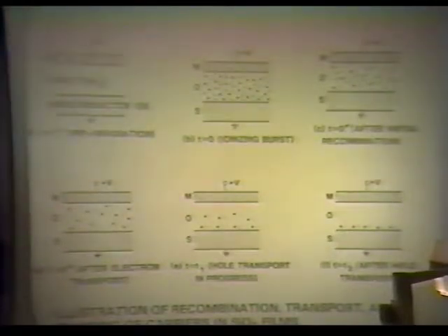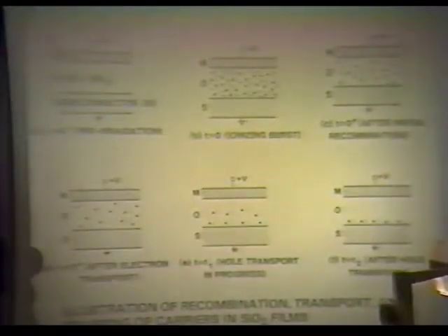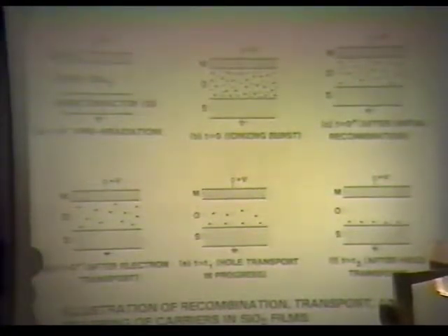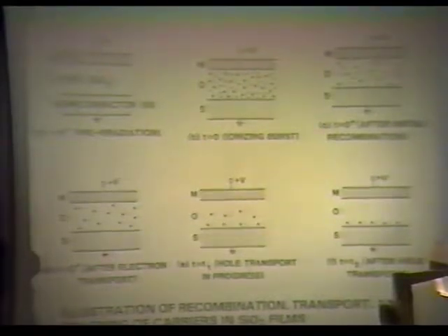Now neutrons, they haven't done much. They've created defects in the silicon here, but you've got so many donors in there that it takes a huge number before you really start affecting the mobility or the transconductance through the channel adequately to really change the operation of the device. But in that poor old oxide, it's got trapped charge in there now, and it doesn't operate the same anymore at all.